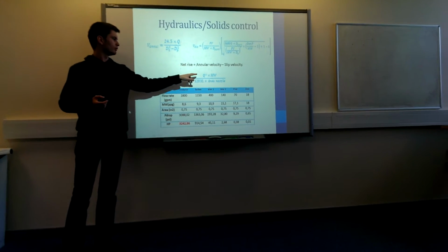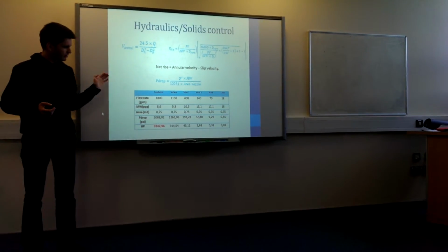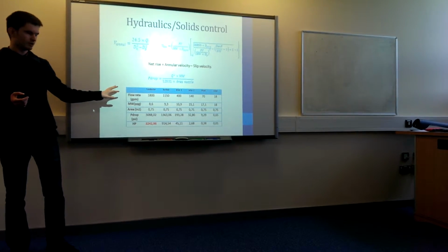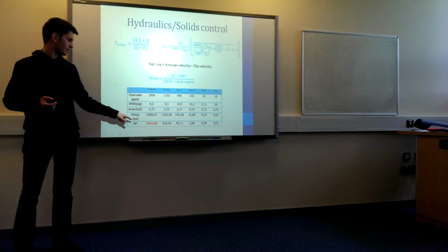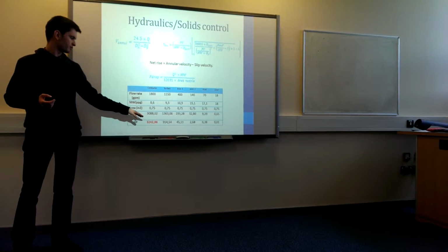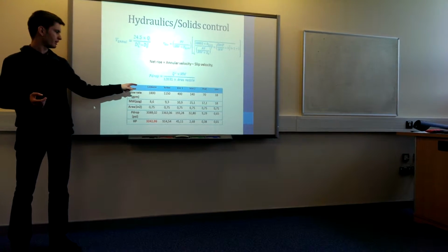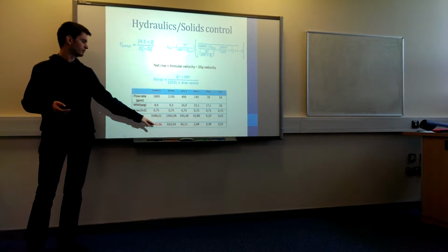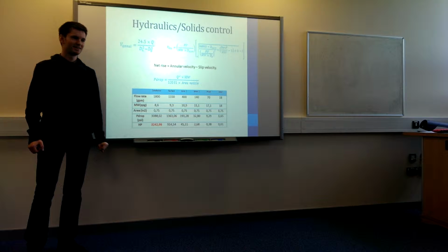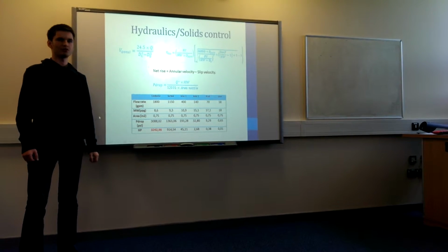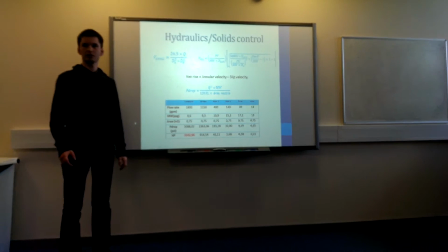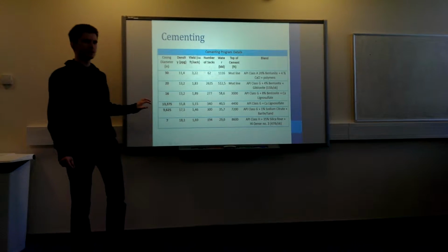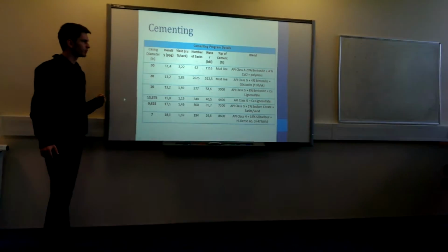We then use this volumetric flow rate to calculate the pressure drop and put all these values into the table. These tables contain all the necessary numbers to calculate the horsepower. We see that the maximum horsepower required was during the conductor casing circulation works, and it was around 3,240 horsepower. That contributed to the final selection of all the hydraulic equipment, and also contributed to the rig sizing procedure. The next step in my work was to create the cementing program.